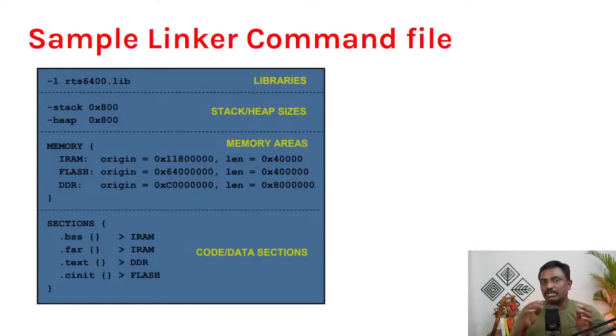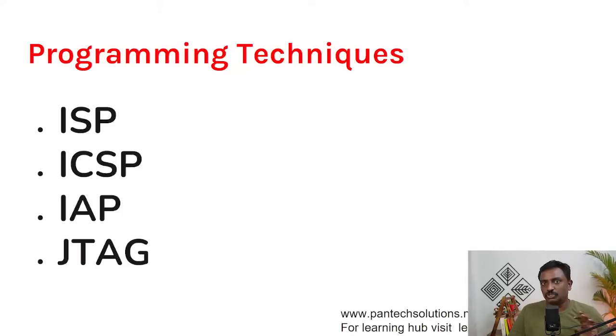You have not come across this on Arduino because Arduino uses the default linker. When you use on-chip memory and your application fits in the on-chip memory, there is no problem. You can go with the default linker. But when you have a complex embedded system design where you interface memories with the microcontroller, in that case you need to know how to edit this linker file. Otherwise, you will not succeed in designing your embedded system. You should know how to edit this linker file, and I will teach you more on it.